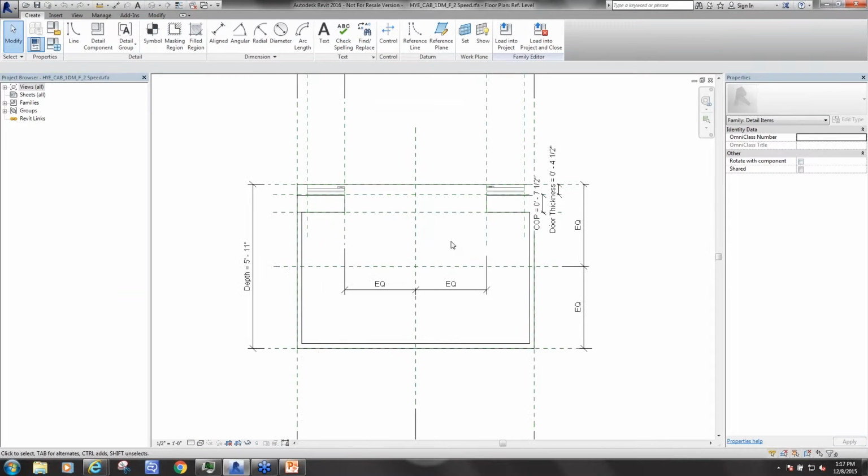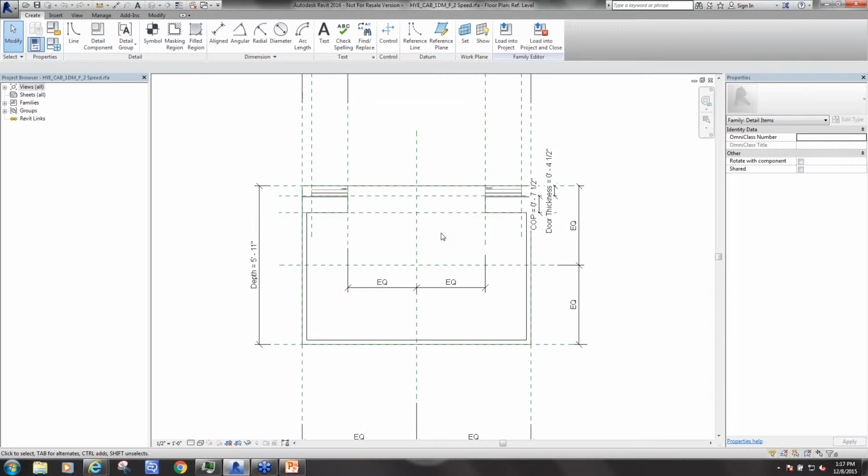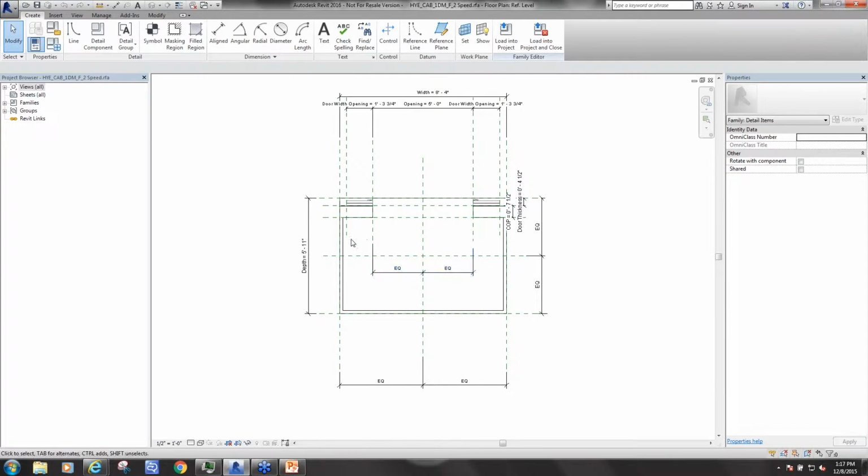So if we start here at the lowest tier, this is our basic 2D family. Because of the scale of this building, we are very careful of what is a 3D family versus a 2D family, because of how big the model is. So what we did is we took this 2D family and are moving it about an invisible 3D line. Really it's just a 2D graphic that I then assign an area of usage.